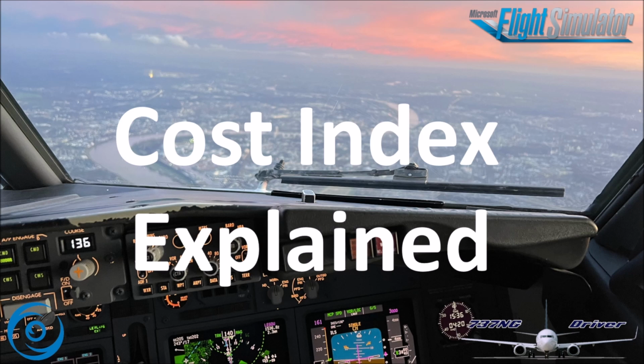And now think about it this way. You're spending around, let's say, 300 kilograms more fuel for a time saving of 8 minutes. Now, is that going to be worth it? The airline's flight operation department will have to decide, but in many cases, the answer is no, that's not worth it, because you might be able to make up only so much with it, but you're using so much fuel. Keep in mind, fuel cost can easily be $1 per kilogram, so you could easily spend an additional $300 for the execution of the flight, while you would save only 8 minutes.